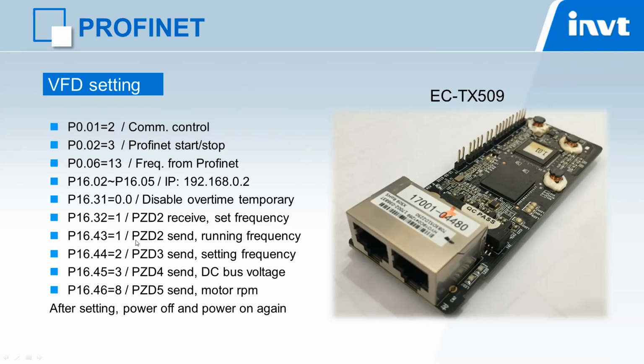P16.43 equals 1 is the PZD2. 43 to 46 is the PZD sent. It means this data will transfer from the inverter to the PLC. You can also set it by yourself. This is just my setting. I transfer the running frequency, setting frequency, DC bus voltage, and the motor RPM. After we set all, after we change this IP address, we must power off and power on again.